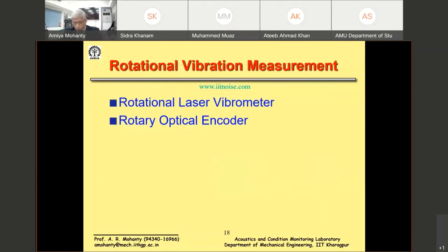And of course, all these measurements which we have talked about were all linear measurements. So again, people have started to find out that in condition monitoring, the faults which occur in the shaft, because of a crack or a bearing fault, show up as torsional vibration, that is speed fluctuation. So this could be best measured if I can measure the torsional vibration.